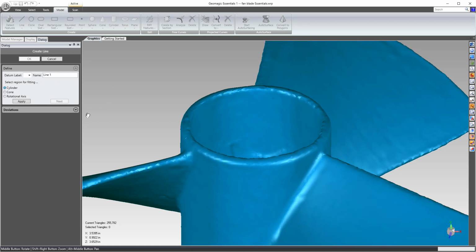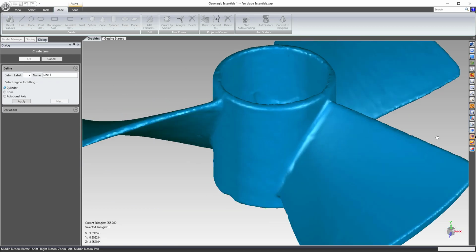cylinder axis. You can use the same tools that we use for selection, the lasso tool, but make sure that you turn off select through and toggle it back over to select visible. So you can window in areas like this to select that outer cylinder to create a cylinder axis. But what I like to do is use this crease angle tool.